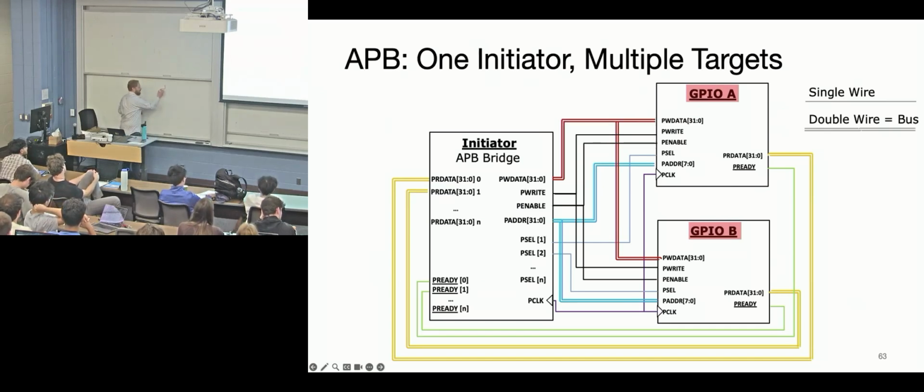I'll say this. From a studying point of view, if you know this circuit and can get your head around how making this a 0 or a 1 will change the output here, you're doing good. This is usually ground. And then, if you want to understand open drain, you just take this part away, okay? And then you say, you know what I really want to do? I really want to make this thing high. There's no way to do it. You cannot force it. You can pull it low. And so sometimes we'll put a resistor here. And so the resistor will pull this thing high.